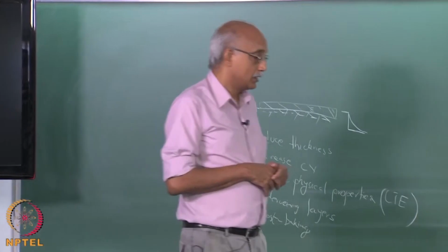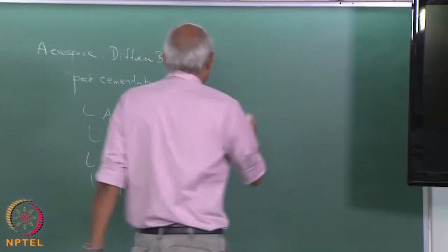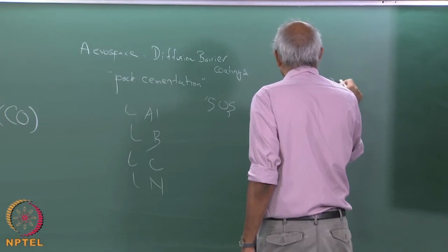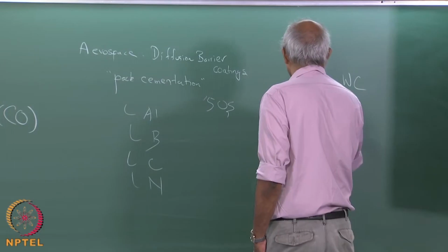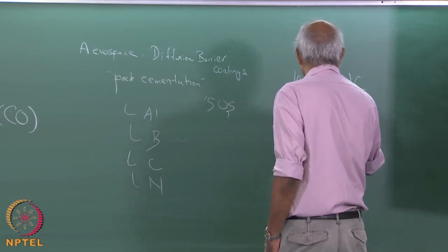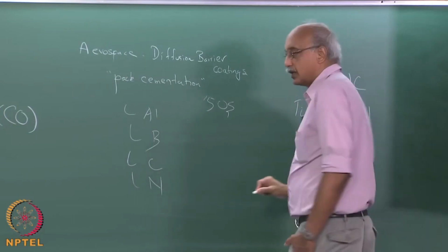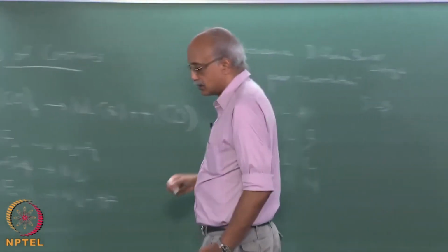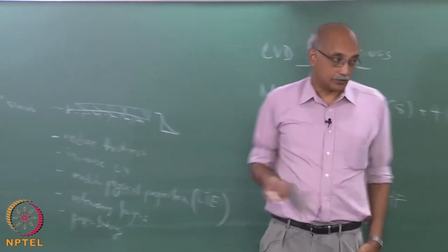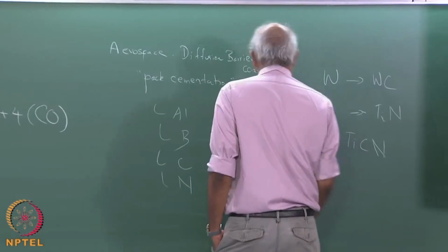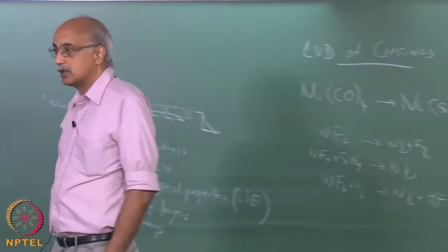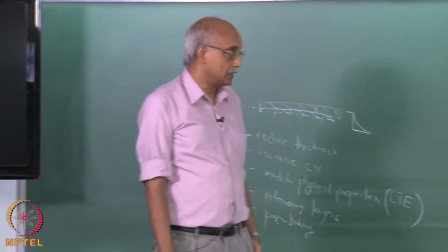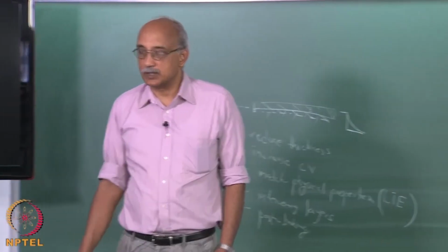For example, if you have a tungsten tool bit, you can coat over it with tungsten carbide, or if you have a titanium tool, you can coat over that with titanium nitride. So, carbides, nitrides, and carbonitrides, TiCN is another popular coating material for tools, and actually there is a fairly large variety of these types of coating materials.